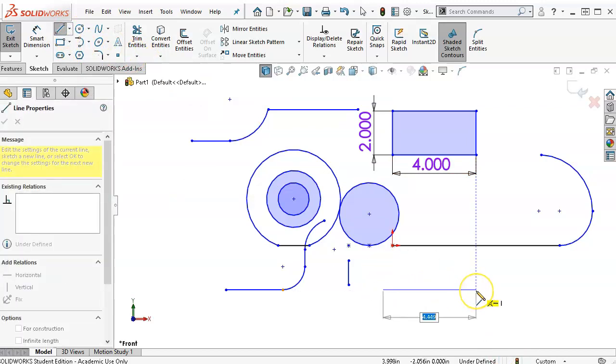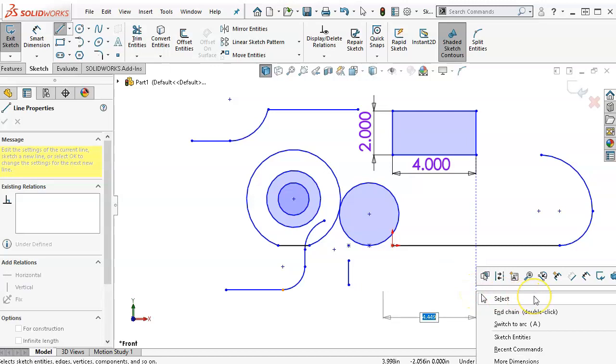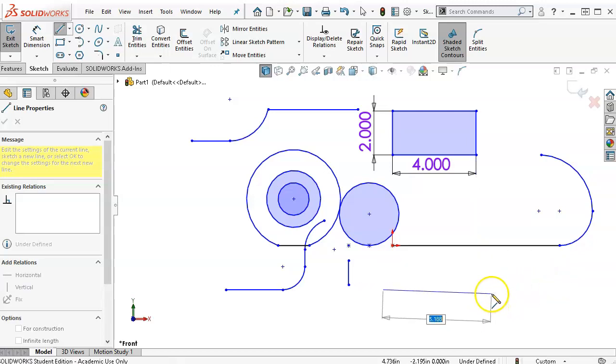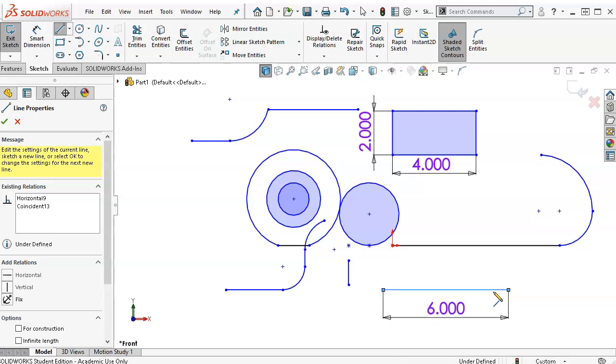I'm going to draw the line. This was a click, and if I right click before I apply the dimension, we have sketch dimension driven. So that was our smart dimension, sketch dimension driven. Not sure why you'd want to force it to be driven, but okay. And then when I come over and say add dimension and place it, I have the yellow boxes for, not sure what it's being coincident to, but it's horizontal and I want it 6 inches long, and then I'll get the dimension.